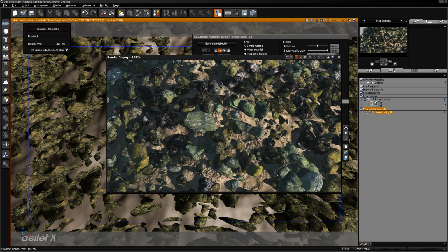So this way you can use one object and be able to distribute its material differently with a Boolean operator so that it is not just a halfway of one material bleeding into another, but actually just saying either we use this material or the next material or the third one in the list if it's the ecosystem or the eco material variance. Or with the seed, it's almost a different offset in material coordinates for every instance.